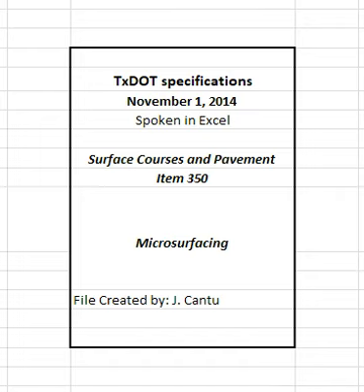4.11.2 Construction joints. Place mixture so that longitudinal joints on the surface course coincide with lane lines, or as directed. Provide longitudinal and transverse joints that are uniform and neat in appearance. Provide construction joints that have limited buildup and no gaps between applications. Joints with buildup will be considered acceptable if no more than 1/2 inch vertical space exists between the pavement surface and a 4 feet straight edge placed perpendicular to the longitudinal joint, and no more than 1/4 inch vertical space exists between the pavement surface and a 4 feet straight edge placed perpendicular to the transverse joint.